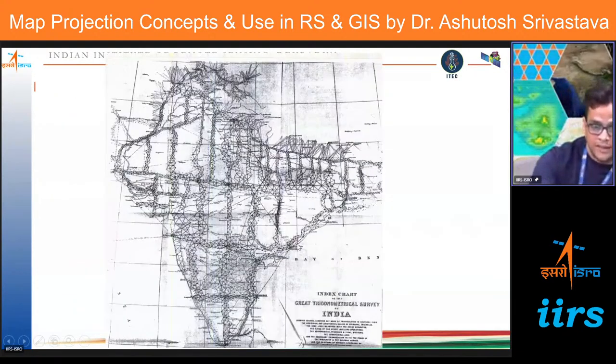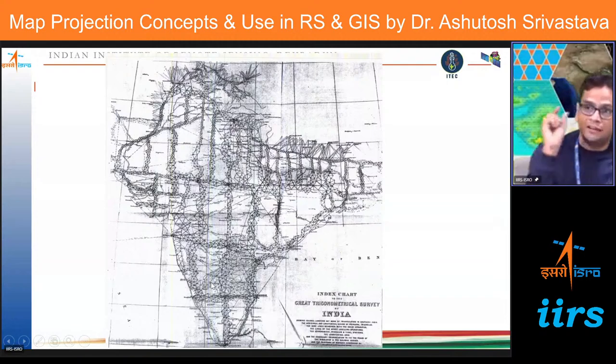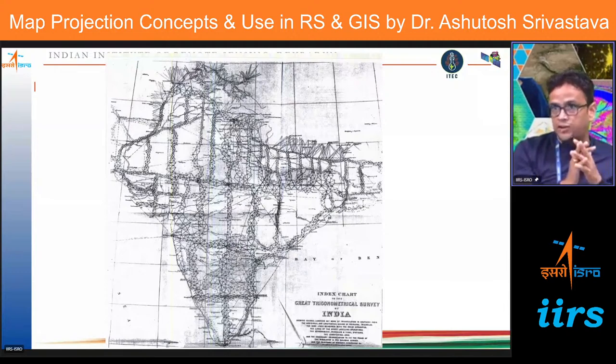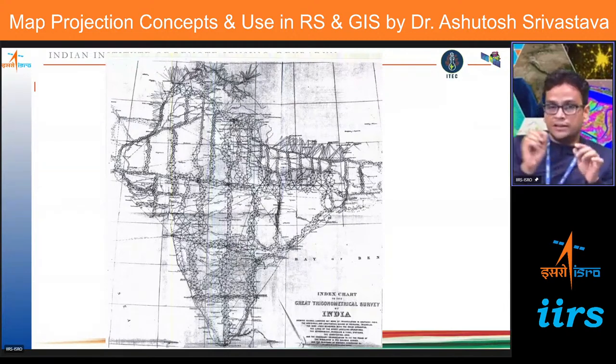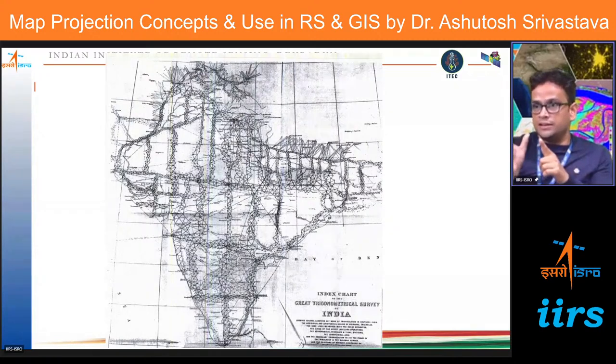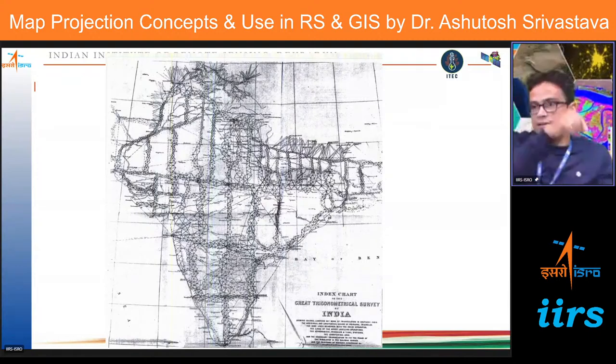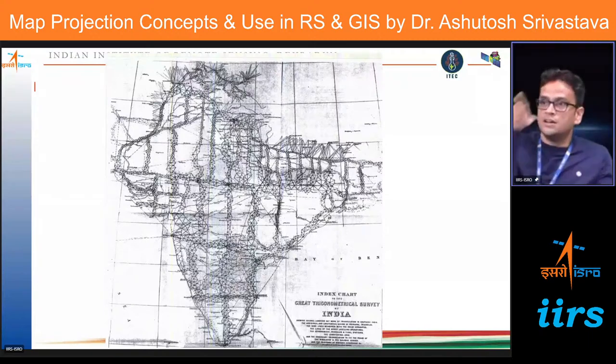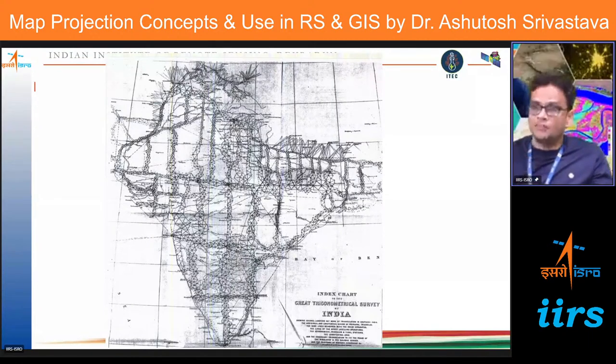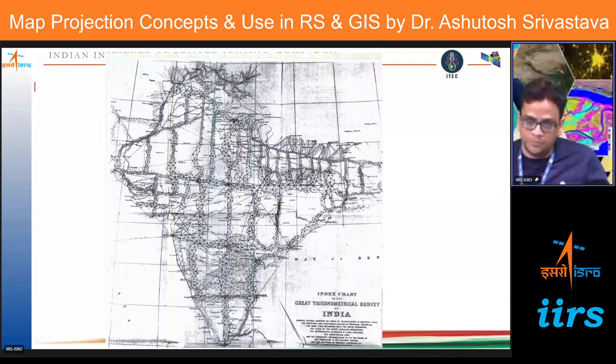So you can say that the Everest ellipsoid, whatever was developed, is also a geocentric kind of thing, because there is only an 800-meter difference in the semi-major axis with today's. So we can understand that though it is a best fit ellipsoid, where local information was used, it still closely matches today's geocentric ellipsoid.